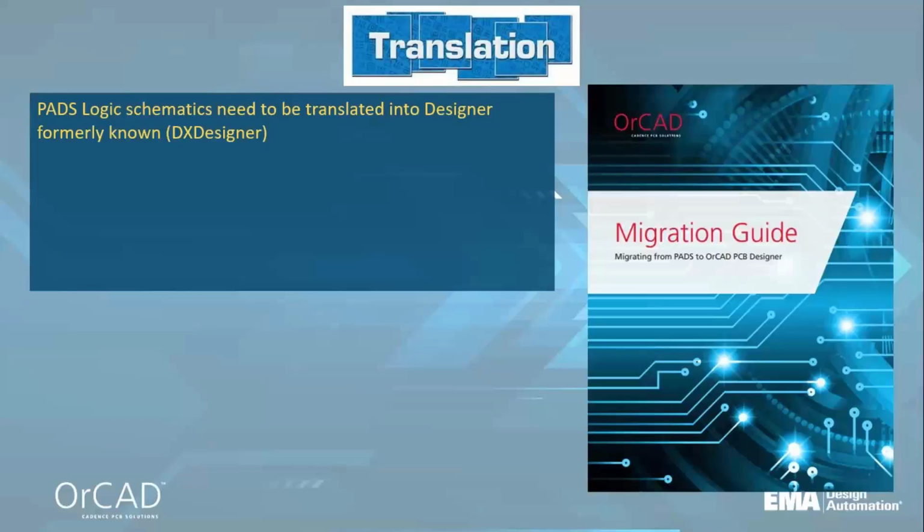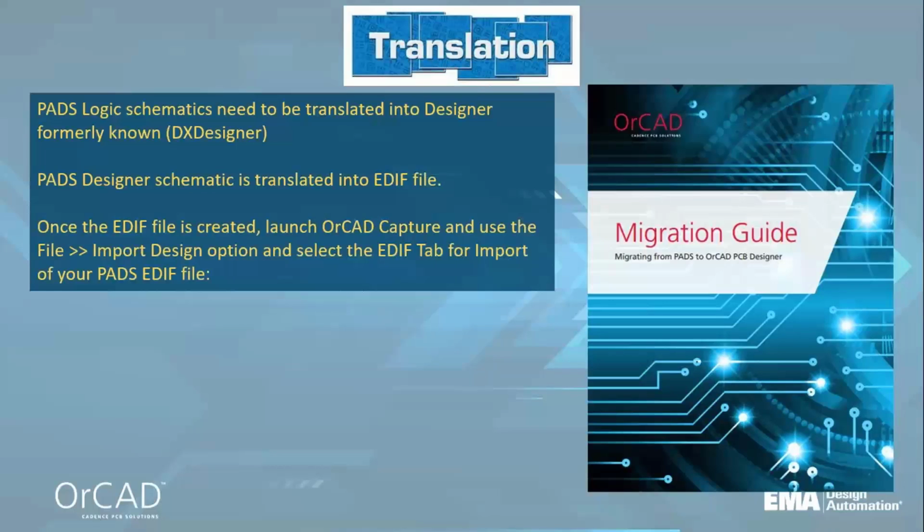One thing that's important to remember, and I'll show you the migration guide when I finish here, is that in order to bring designs in, say from Logic or Designer into OrCAD, Logic needs to be brought into DxDesigner, and then from there we can create an EDIF file. Once the design is in Designer, it's easy to bring Logic into Mentor's Designer tools, and then translate that to an EDIF file. Once that EDIF file is created, you're going to want to launch OrCAD and use the File Import Design, select that EDIF tab, and import your design file.